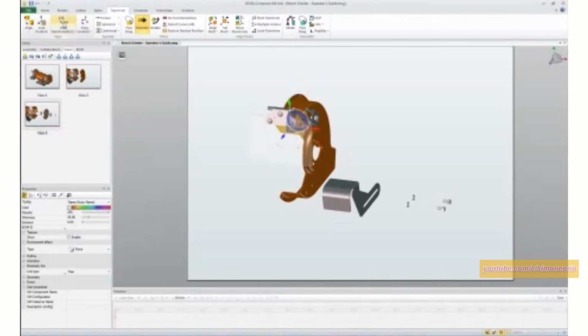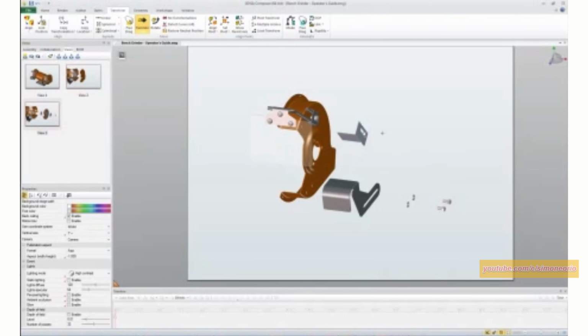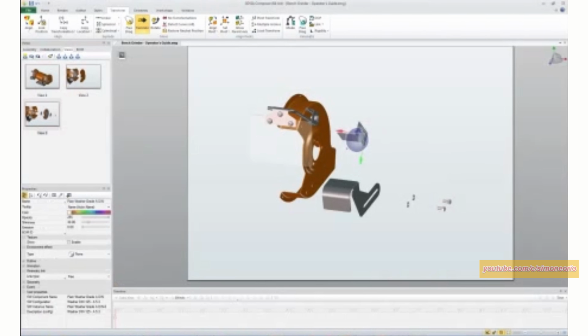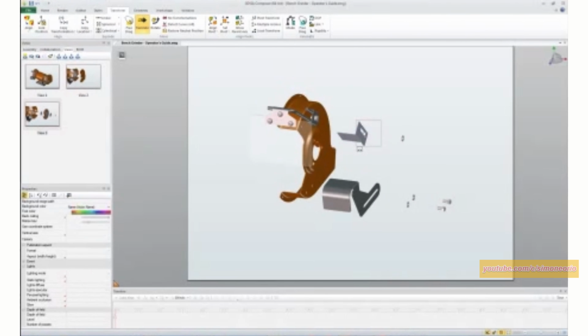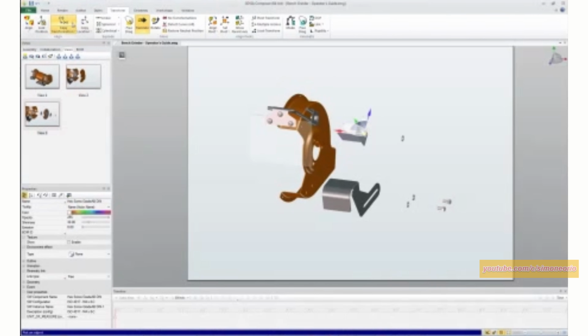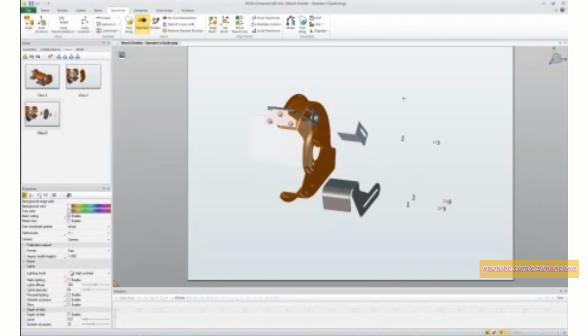And what I can do is I can actually copy a location that I've previously used. So once again, let me go ahead and select just the washer this time. And again, I can copy the location that I've used to create this. So this is saving a bunch of time by reutilizing exploded steps, essentially, to do all this.